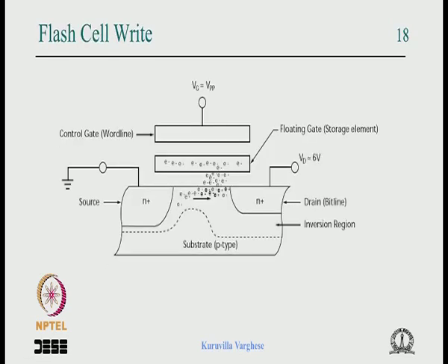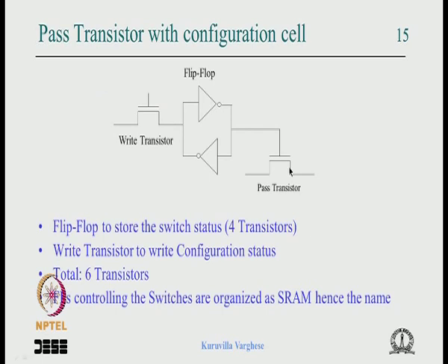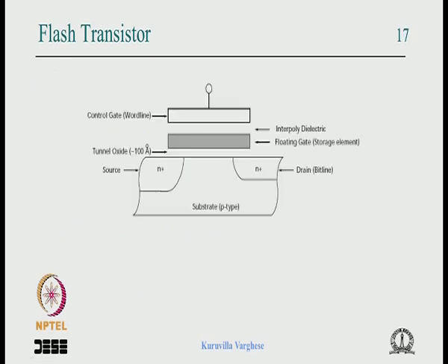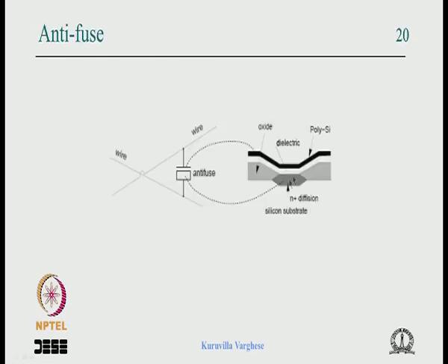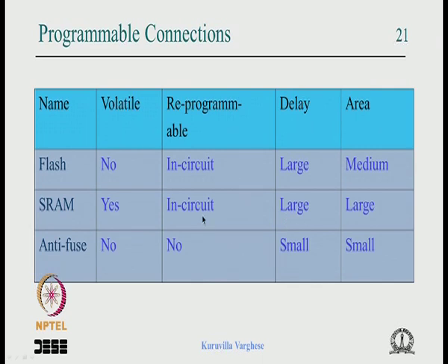But in SRAM FPGAs, you know that the status of these flip-flops has to be stored somewhere, and at power on it has to be programmed, and if somebody can read those memories then this design can be pirated. But nowadays there are encryption technologies available to protect the configuration file which is stored in a memory. But this has an additional advantage, and the summary is shown here.